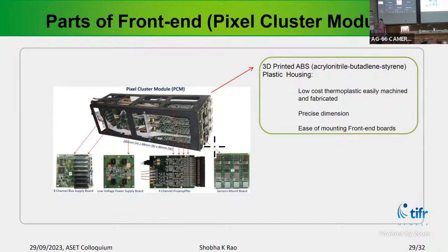But that is because you are limiting the bias that way, no? Not that, that's why the noise will be increased. I also saw that the pole zero cancellation of the amplifier is poor. That is why you get a lot of fuzz on the other end of your pulse.